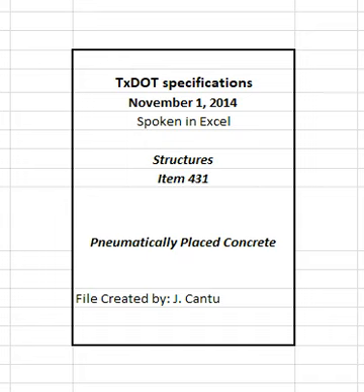Provide experienced personnel able to produce concrete satisfying plan requirements and of uniform quality as required. Provide documentation of nozzle operators' qualification for the process proposed and orientation of the application meeting the minimum requirements when shown on the plans. Demonstrate nozzle operators' abilities by constructing test panels before commencement of work. Orient test panels to match application direction of placement. Include reinforcing steel in the test panel with similar spacing as in member. Qualification test panels may be used for mix verification in accordance with Section 431.2.4, proportioning and mixing.